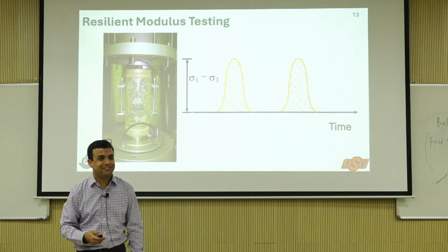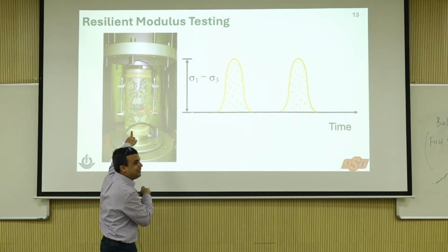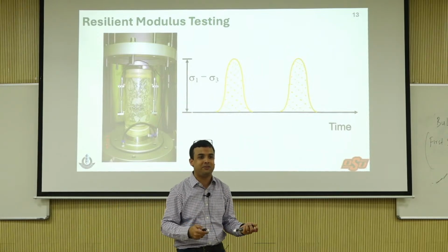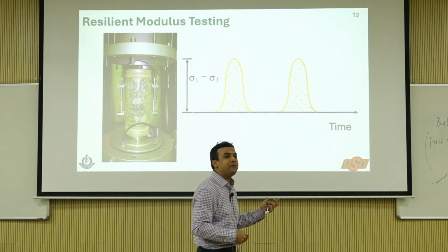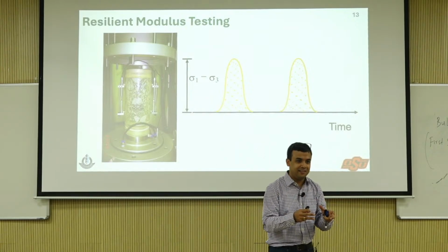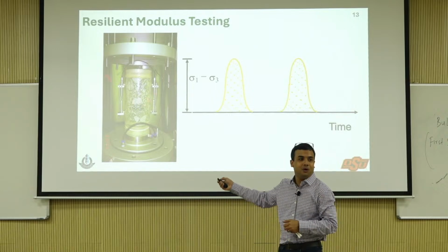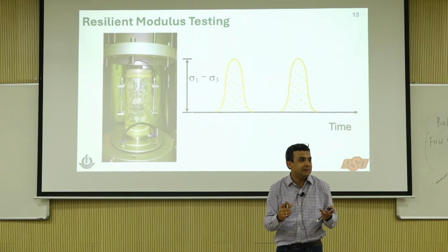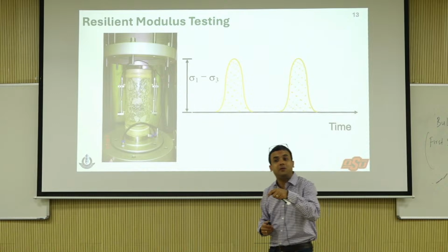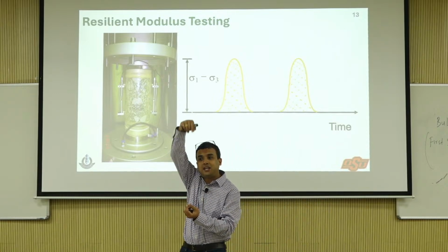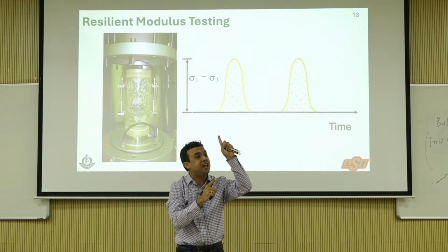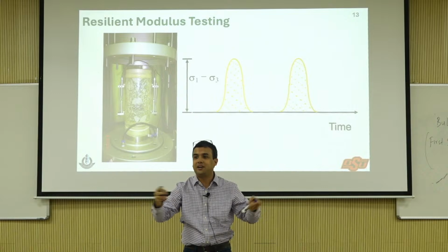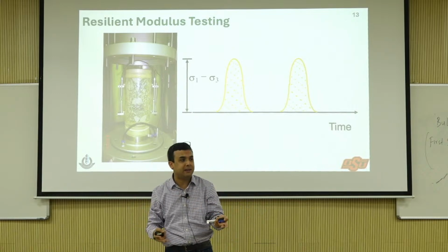It will break. Your LVDT will break because you are on the sample here, right? It's going to bulge. You're going to ruin your LVDT. Your advisor is going to be extremely upset at you, right? So what I'm trying to say is, shear strength testing, you usually don't do on-sample deformation measurement because your LVDT is going to break. That is the reason yesterday when you did the data analysis, we were talking about the actuator LVDT. And that is the reason the axial LVDT 1, 2, 3 and radial LVDT data were all 0. Do you understand? Because we didn't mount it because it would break.